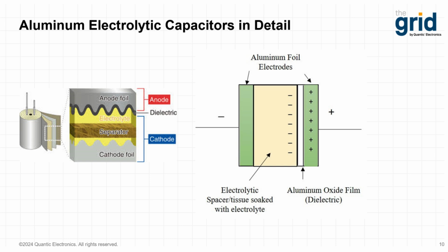Now, a second aluminum foil, known as the cathode foil, makes electrical contact with the electrolyte. Separated by a paper to ensure the two foils do not make electrical contact, the two foils are wound together. After processing, the wound capacitor is put into an aluminum case and sealed.